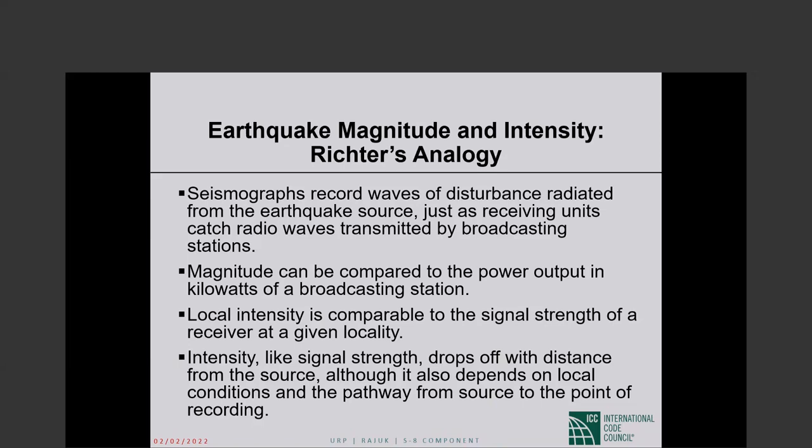And finally, the site conditions at the site, because if you have rock at your site, there isn't any amplification of the motion that will arrive at the site. But if you have soft soil overlying rock at your site, the ground motion that arrives in the rock at your site will be amplified by the overlying soft soils.